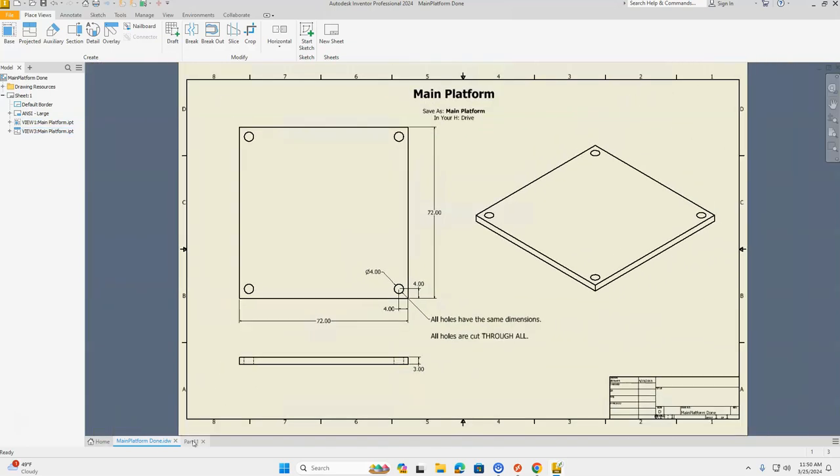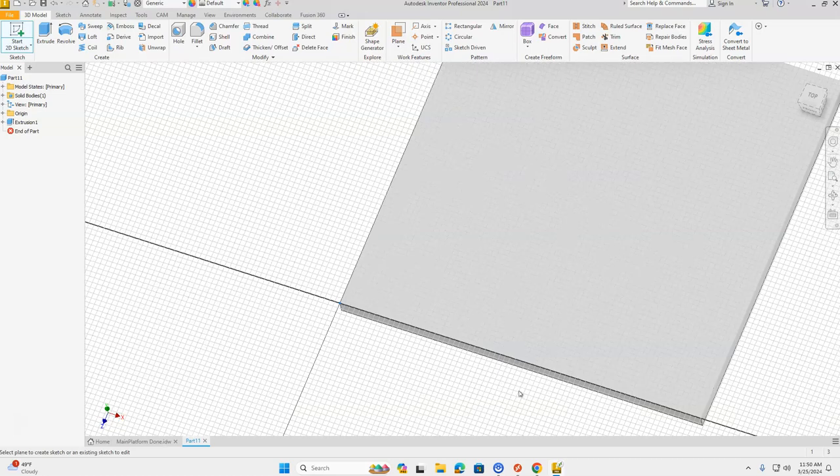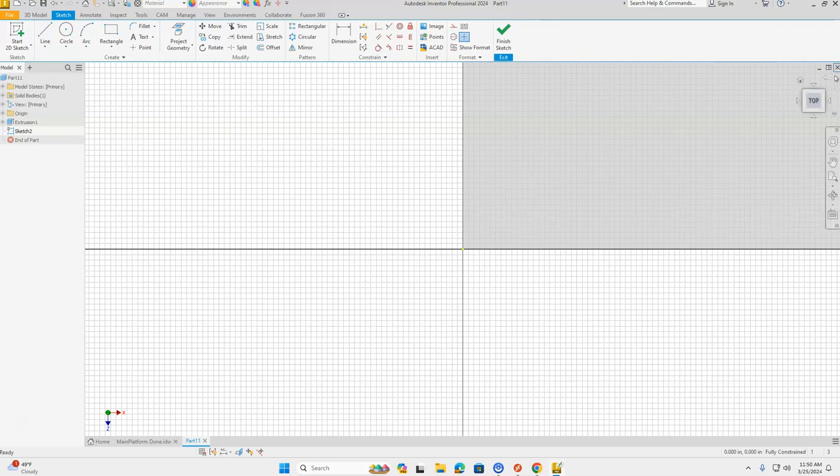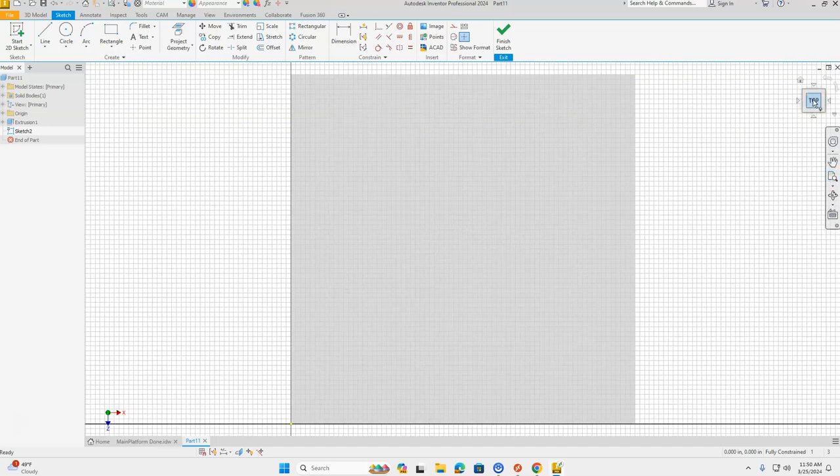All right. Let's go back to our drawing and place those points. So I'm going to take a 2D sketch, place it on my top view. And it goes off the screen. We know the trick of clicking our magnifying glass piece of paper, or you could select top in your World View Cube. Both will do the same for you.